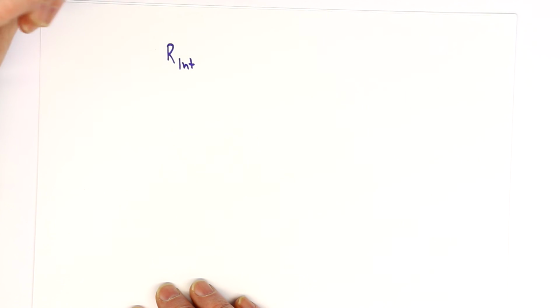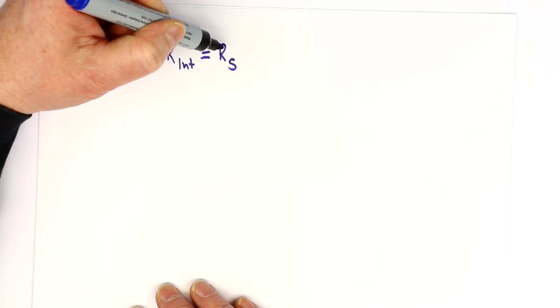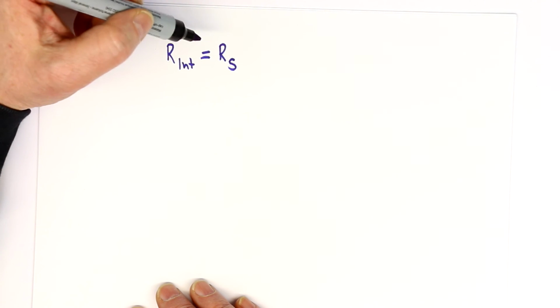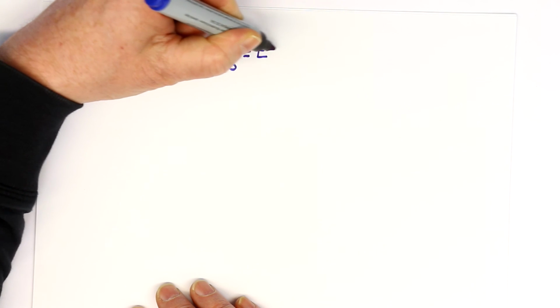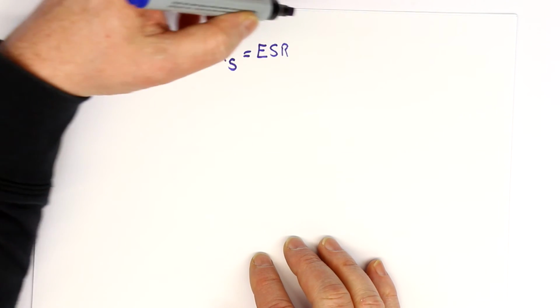So let's remember this quite important fact. When you are dealing with the internal resistance of a transformer, you should not use the DC resistance, which you measure with your multimeter. Either measure it with your ESR meter, if you have one at hand, and ideally at 50 Hertz in Europe or 60 Hertz in other regions, no matter whether you call it series resistance or equivalent series resistance.